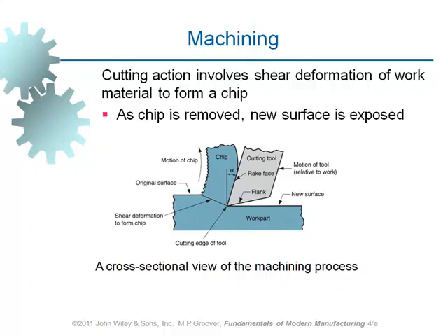And there are a number of angles and geometry of the cutting tool which is of importance in the success of a machining operation. The top face of the cutting tool has got a cutting angle which is called the rake angle, and the magnitude of this angle is being defined by parameter alpha, which stands for the rake angle.